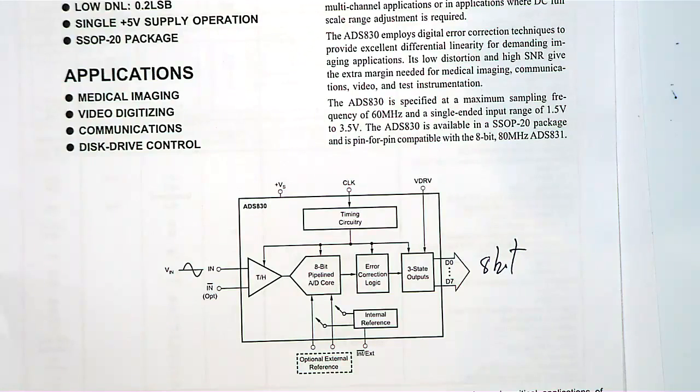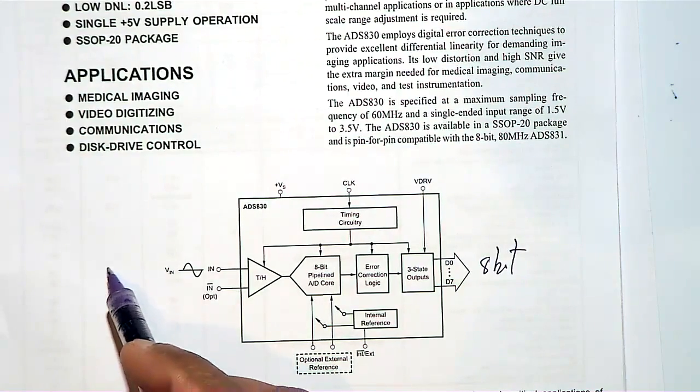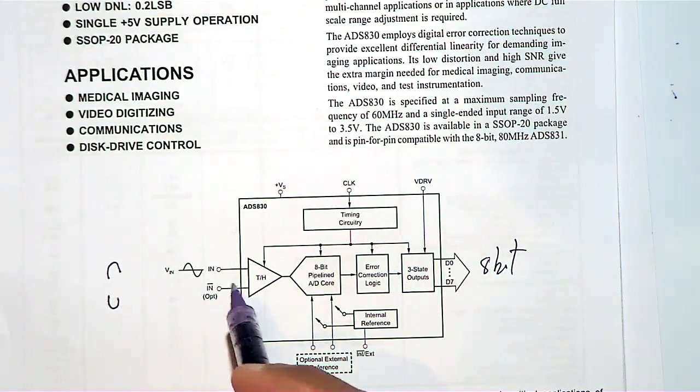Why we need it is when you have noisy signals, even the low pass filter will not be able to prevent all the noise. You will see the design complexity. In that case, the ADC manufacturer recommends you to use differential mode operation. Differential mode means the same signal, here it is positive, then you make it negative and connect it here. Sometimes the differential is much better, because even after the low pass filter you will have noise. Then how will you convert?